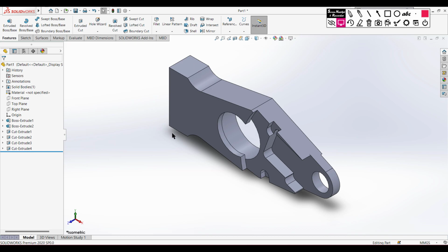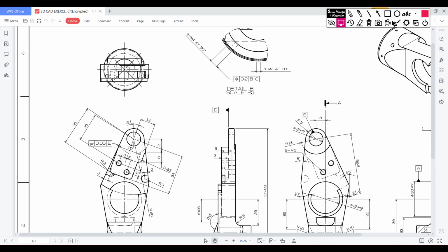So this portion has been done, and in our sketch we can see some holes here and here, and these holes are M5 holes. I am not using the hole wizard here because it will make the video longer. So I am going to use a normal extrude cut circle instead of an M5 hole. Also for this portion there are M4 holes, so I will use an extrude cut circle of 4 radius, and an extrude cut circle of 2 radius. Or if you have time you can use the M4 hole wizard as you want.